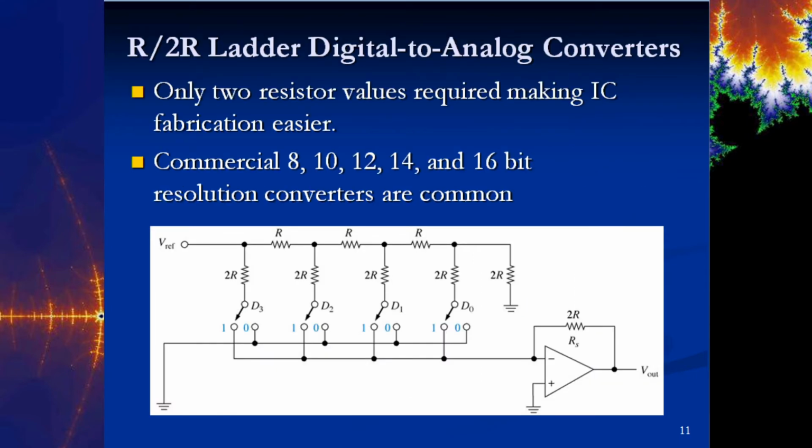Now to switch gears a little bit, take you back to your first circuits class, where we learned about the R2R ladder network, and it had a very similar setup to what we saw with the binary weighted system. If we do the same thing where every branch has a switch on it, and if it's on one switch it goes to ground, the other switch is a high. Here we've got all of these connected together, so we have a predictable current coming down each branch.